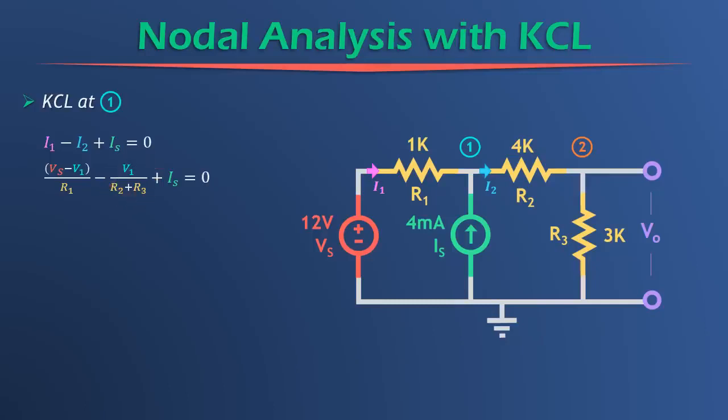Why did we do that? Well, it's because we lumped together R2 and R3 as one resistor, because they are in series, as we learned before. And we can disregard this whole wire kind of flying off here, because there's no current in that wire. It's not going anywhere. It's not doing anything. So you can completely disregard that wire and just call this a series connection of R2 and R3.